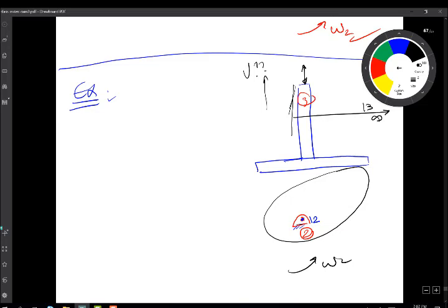Now, so again, I want to find point 2, 3. So that's my strategy because this point will be on 2. So I can find its velocity on 2 because I know omega 2. So I can multiply omega 2 times the distance from the pivot to the point. And then it will be on 3 automatically. This will give me the velocity of the slider.